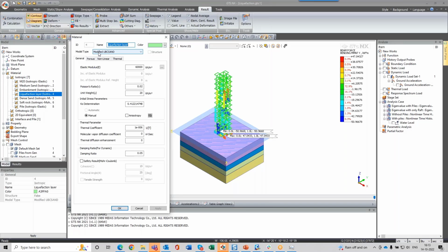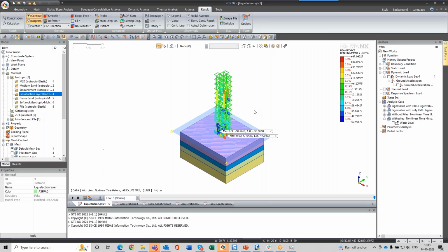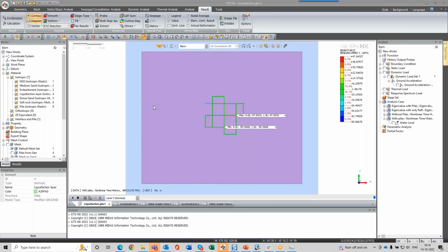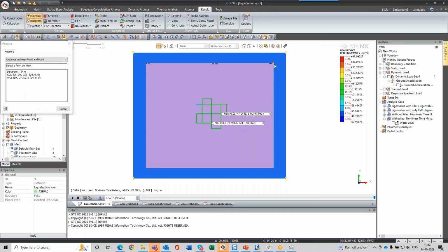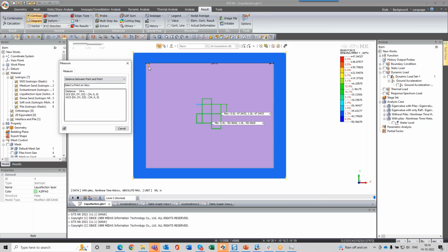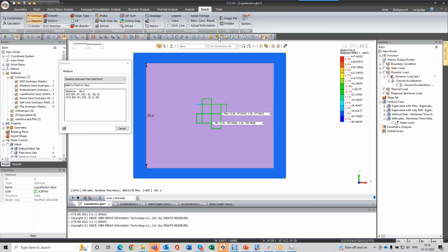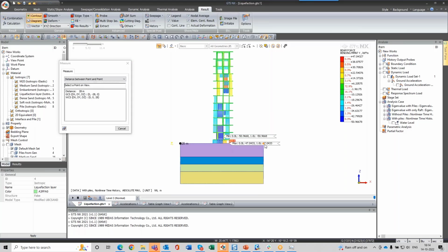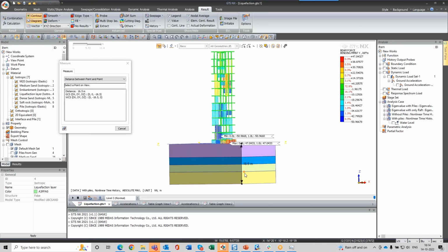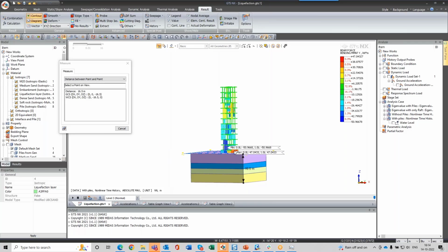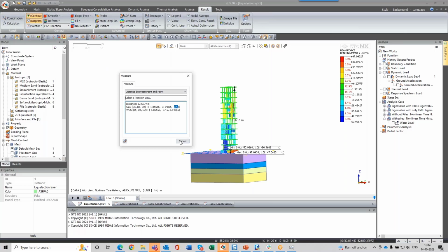So it's not an elastic analysis which I have taken into consideration, but it's the nonlinear material properties that have been considered in this model. What's the size of this model approximately? You want to see the size? Yeah, just an idea of the size of the model itself. 34 meters by 28, and you can have the depth of around 16.2, and there's a building as well. So somewhere around the Z depth is 37.5.